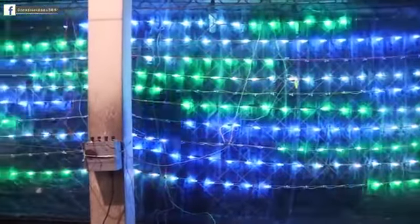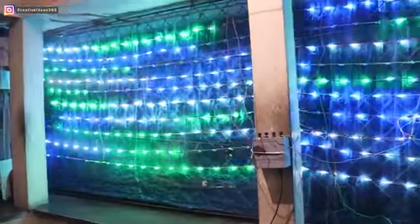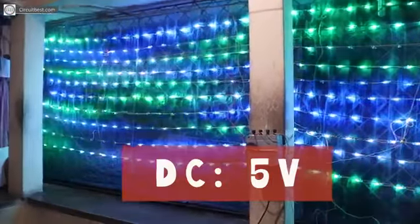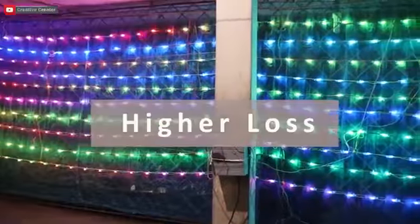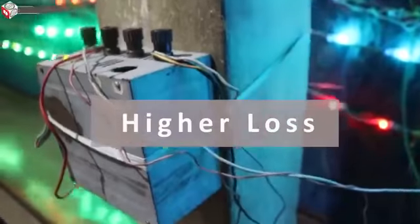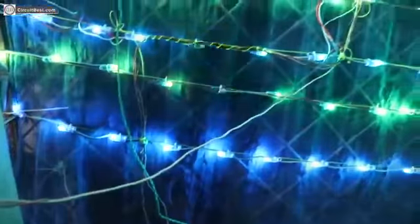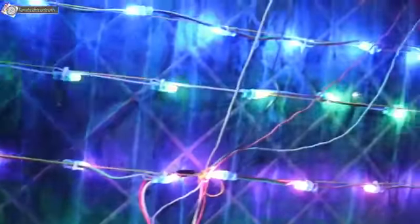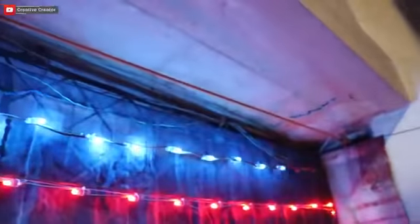One thing you should note is that WS2811 LEDs run on DC 5 volts. You all know that DC has some great losses, so you should use high gauge wires, otherwise you will see that the first LED near the power supply will glow higher and the last LED will glow lower. In my case, I have given power to each and every LED strip individually.